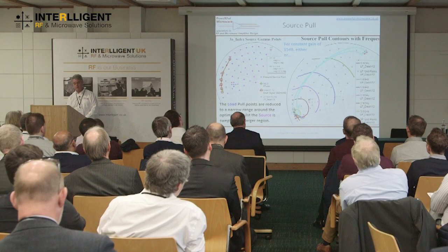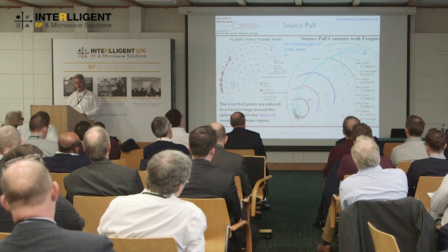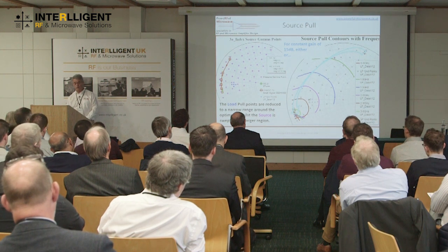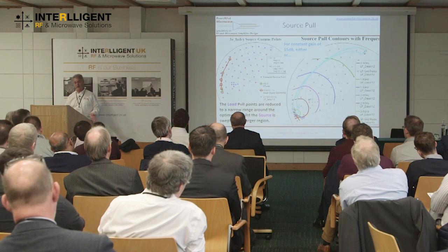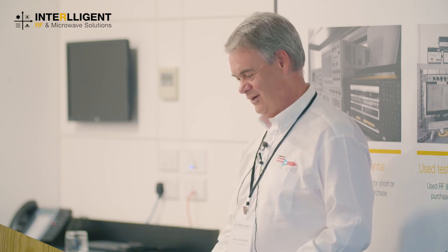And so if we designed an impedance matching circuit that went from this 0.8 up here and went through these contours, and at each frequency they matched up with a contour, so at gigahertz we were on this contour somewhere, we would get a flat gain. Unfortunately, that trajectory is really difficult to design in a real matching circuit.